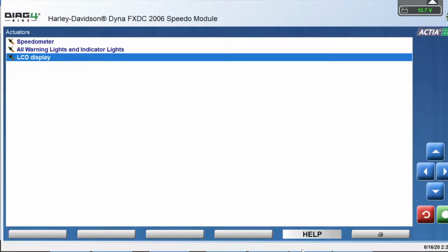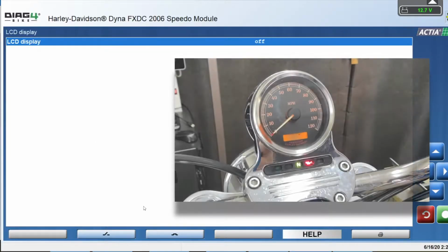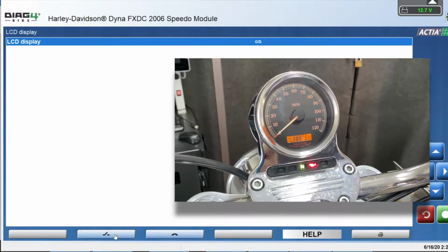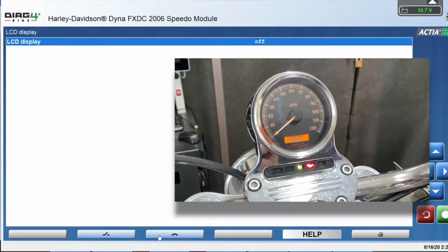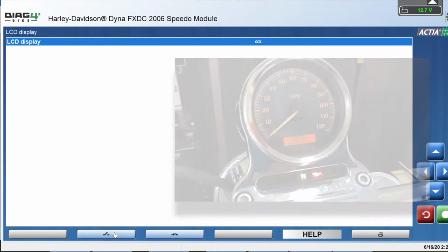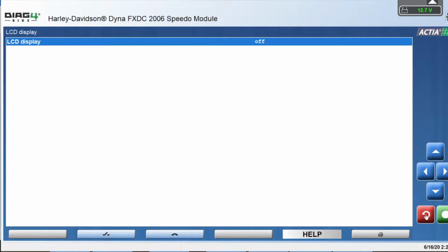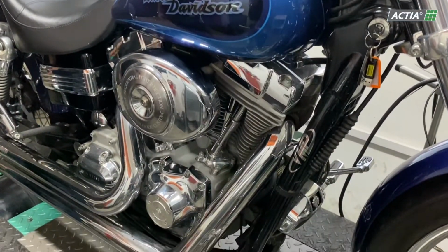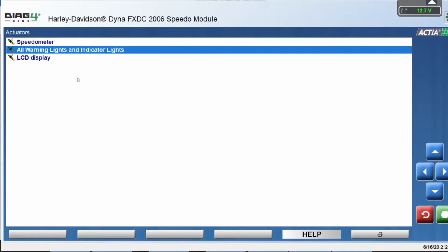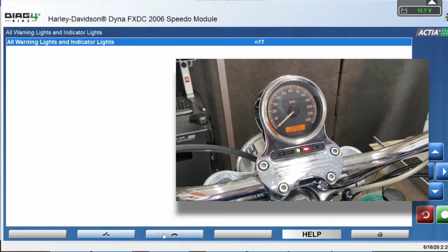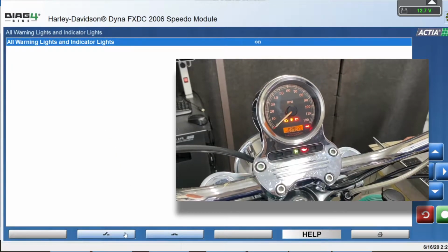Actuator test is a very important diagnostic operation that tests the hardware connection between the control unit's outputs and the actuators it controls. This operation also checks the connection of the actuator and its functionality. The majority of tests must be performed with the engine turned off. Others have to be done both with the engine turned off and on, and some require that the engine be running. The vehicle should be inactive, in a stable position, secured against spontaneous motion.